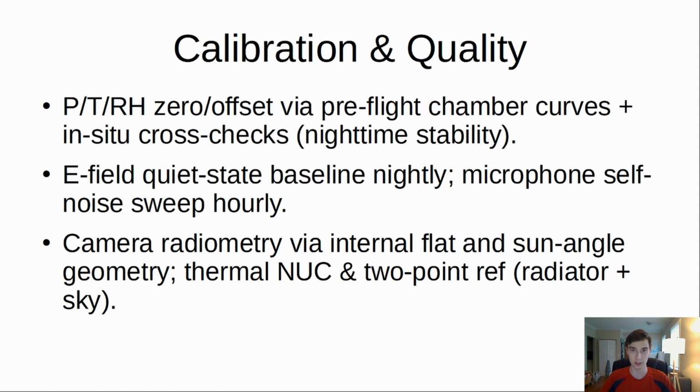This is just for stability during the nighttime, because the nominal temperature is going to be negative 60 degrees for most of these probes. And most electronics are mil standard rated, which is negative 40. That's 20 below. And I talked about the mean. So we're going to get colder than that. Things are going to fail. Things are going to go weird.